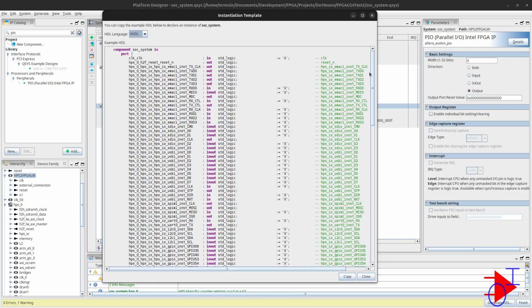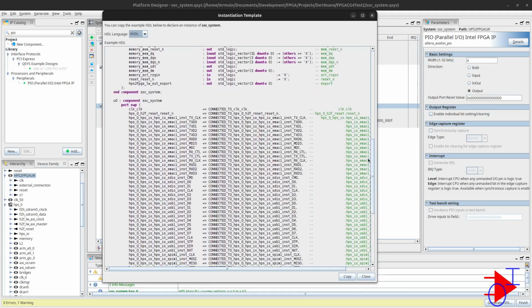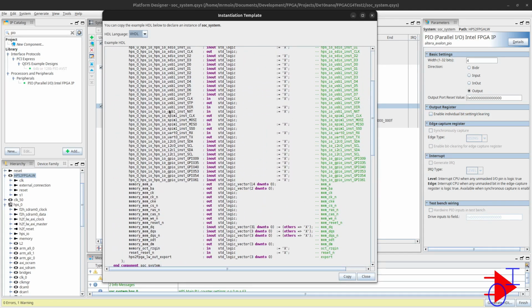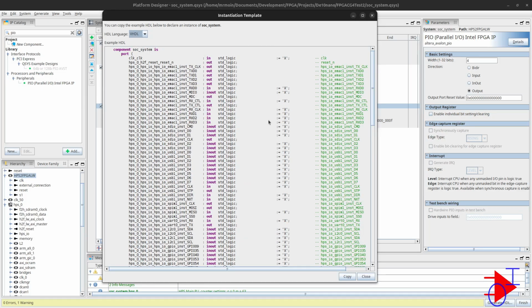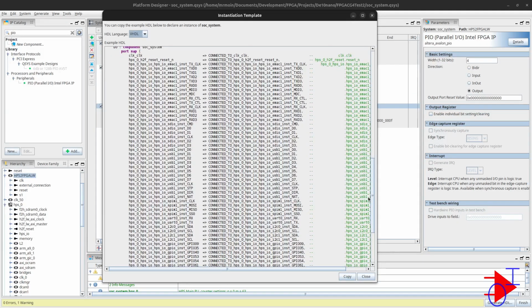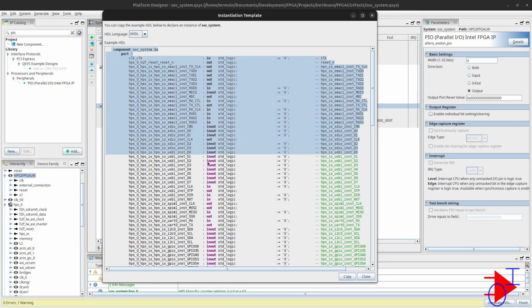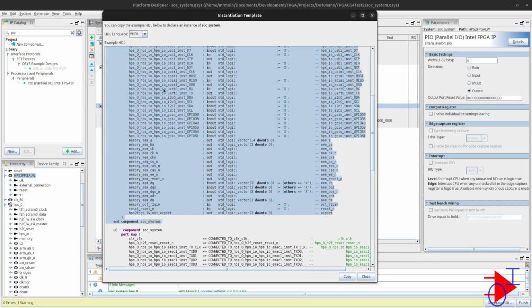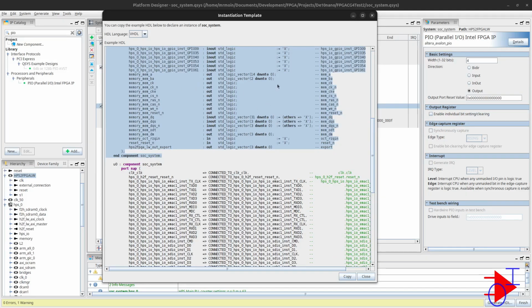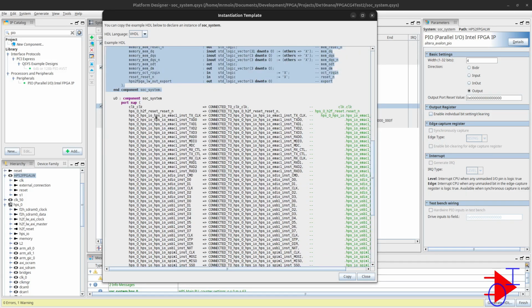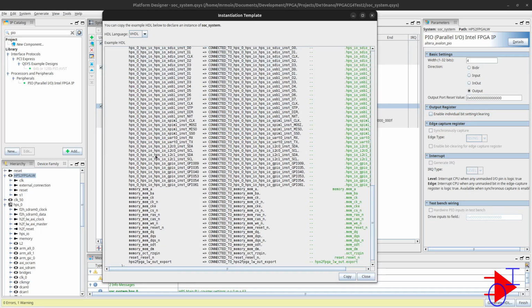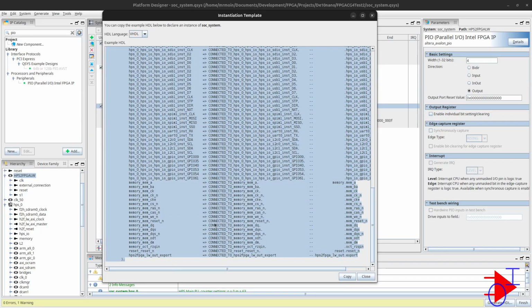First, you're going to include the QSys project, but then in order to make connections to your connection points in the VHDL, you must include these components and then make connections. So basically, this is the component, the SOC system file that we generated. This is the component for that file. All the declarations, the bit lengths, and then the port maps for each bit where it's going to map.